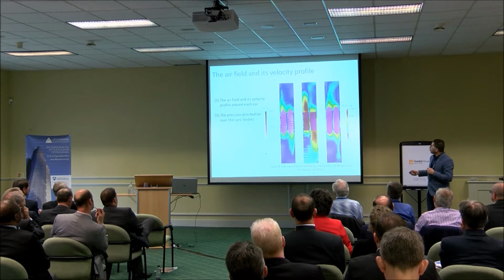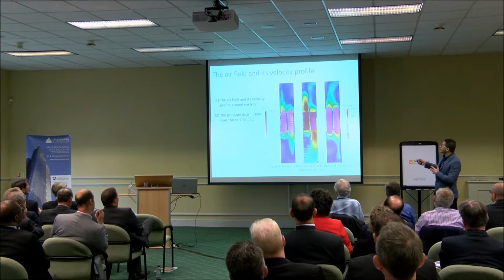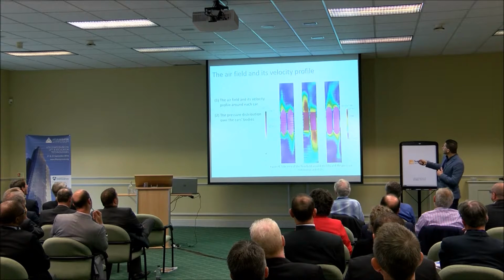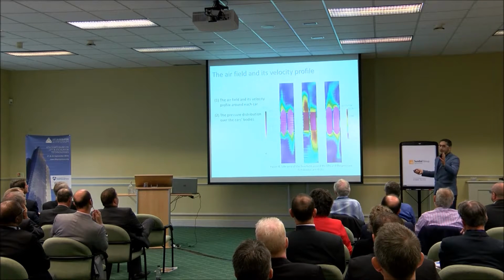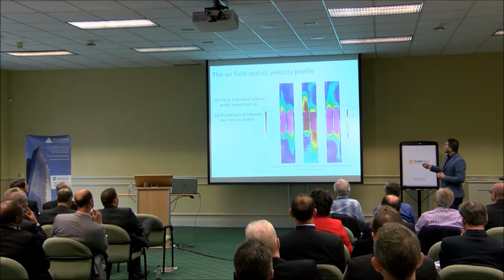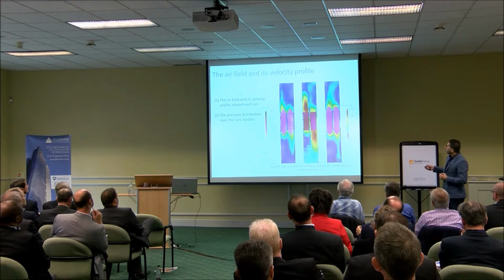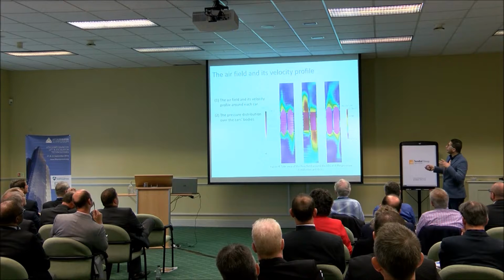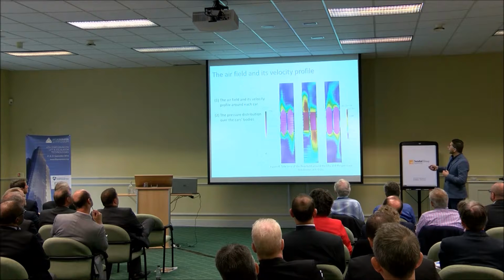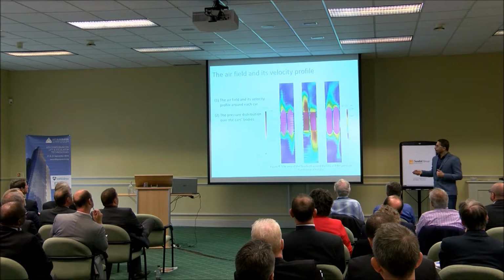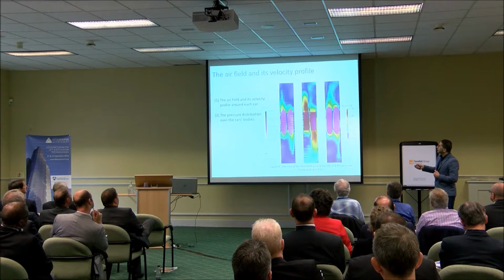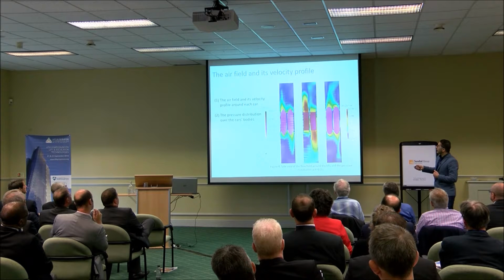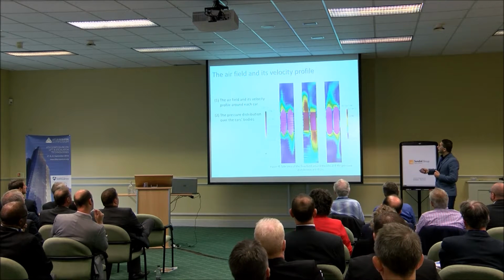Now, this figure shows the air field and its velocity profile around each car, and it also shows the pressure distribution over the car's bodies. It can be seen that the pressure value that acts on the flat lift is higher than other shapes. Also, at the crossing event, it's clear that the air pressure acting on the triangular lift is less than the air pressure that acts on the hemicylindrical lift.